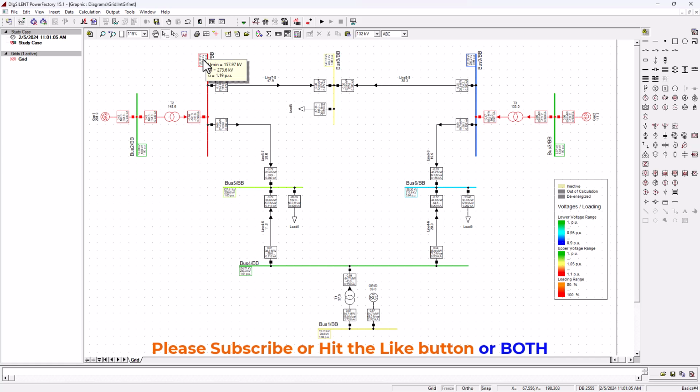So we need to look into the reason why this bus bar is overloaded. Now, this is precisely the reason why we did this analysis, so that we can see where the problems are on our network. Now, here we're not even placing any load on bus bar 7. The only loading on bus bar 7 is that bus bar 5 is demanding, and bus bar 8 is also demanding. Now, imagine if we have to put a load here on bus bar 7, the situation is just going to get worse, right? Because our slack bus can just do so much control. So this is where we need to readjust and make sure things are running as smoothly as possible to eliminate the problem in our power system network.